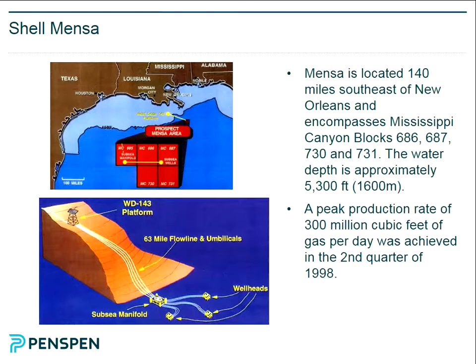And this is the Mensa manifold. I don't know if you've studied deep water fields, but you can't use conventional divers at all, so they have to use these made-up spools with vertical stabbing connections. So you'd lower something like this down to the seabed, and then you connect each well individually with these lowered-in vertical stabbing connections. So at the time, it was the longest tieback in the world, 109 kilometres.